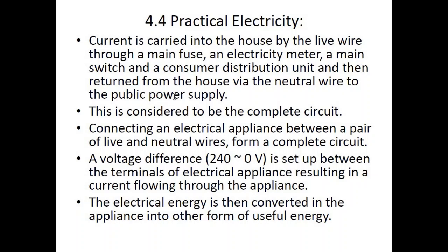If they were connected in series, if one appliance burned out, current would not have been passed through it and reached other appliances. So even a single bulb in your house burning out would have cut off the electricity supply to your whole house, to all the appliances in your house, if your household circuit was joined together in series. So always remember, the electric circuit that connects all the appliances inside your house is always made in parallel.